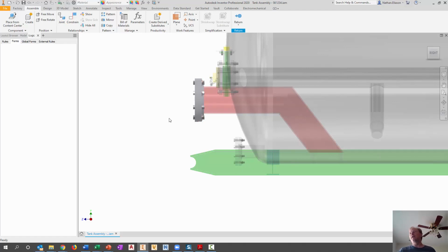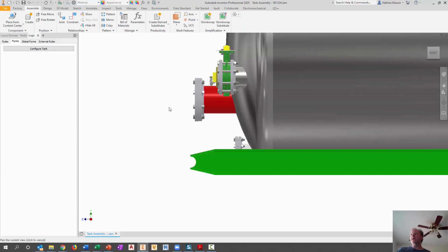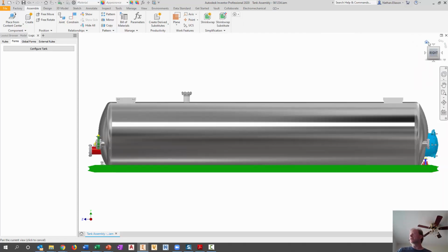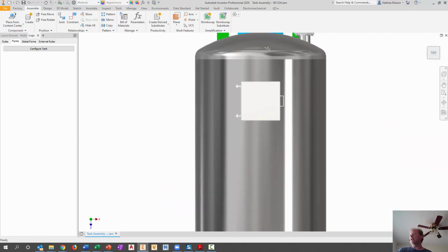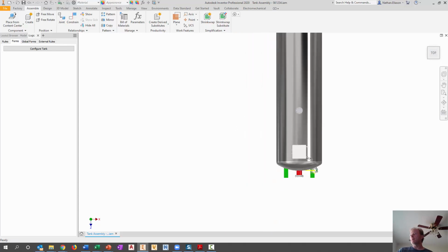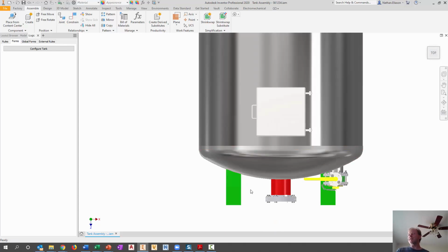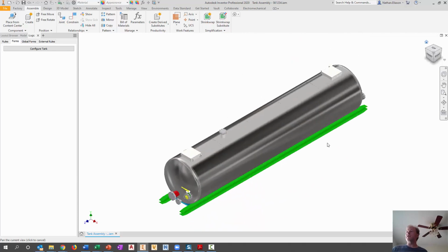So you can see how we can build our logic so that we allow the users to configure a tank exactly the way they need. Last I want to point out, notice that we have a 12-inch offset on the rear, but if I go to my front, we only have a 4-inch offset. So again, all of this code is in there.